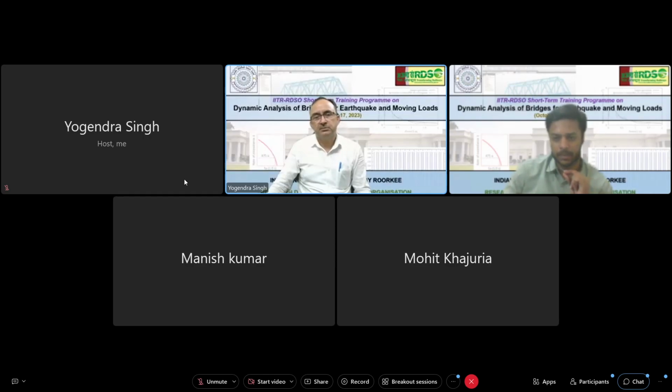Okay, sir. Mr. Dharmendra is asking for a nonlinear dynamic study like IDA, what will I do if a sufficient number of ground motion data are not available at the site? Can I use other ground motion data in case of insufficient ground motion? Actually, you have to use the best ground motions which are available. There is no specific limit defined that the ground motion should be within the range. Whatever is best consistent with your site and source conditions, use those. Make your best effort through all the available websites. You can obtain from there.